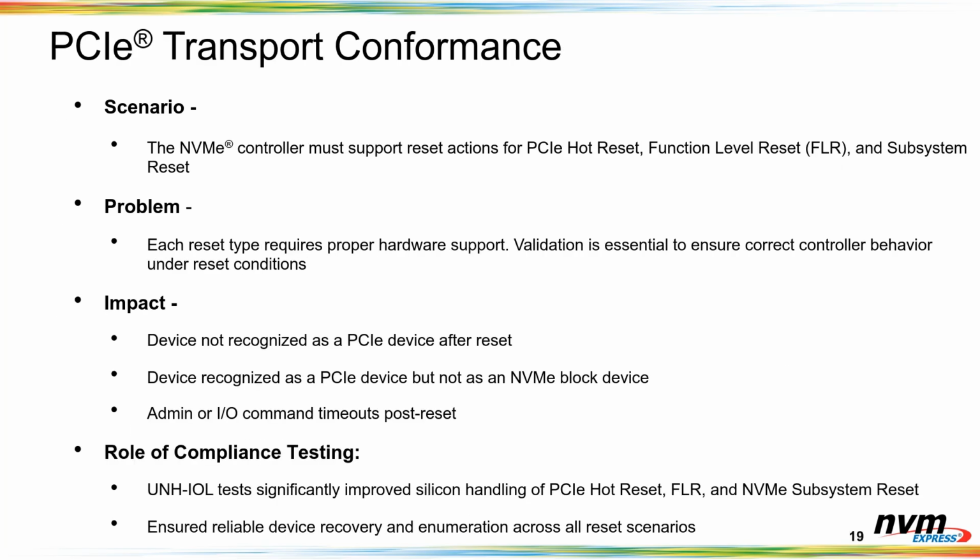So the next is PCIe transport conformance. The controller must support different reset actions for PCIe: PCIe hot reset, function level reset. Each reset type requires proper hardware support, and validation is required to ensure correct controller behavior under reset conditions.